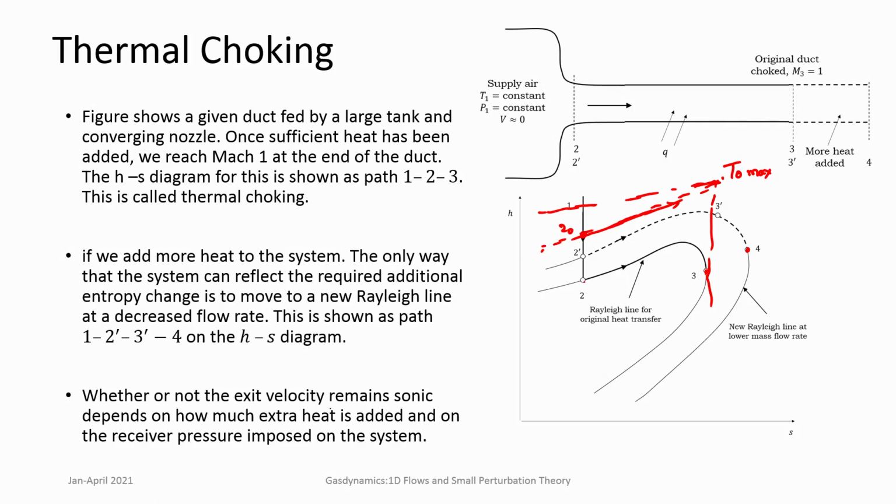One is that if you want the flow to remain on the same Rayleigh curve, then the point 2 should be shifted to some other location, 2 double prime, where now there is scope available for adding more heat, but this implies greater pressures. So, more pumping and so on. The other solution that can occur is simply the flow just shifts to another Rayleigh line, where G is smaller, G decreases, that means mass flow decreases.